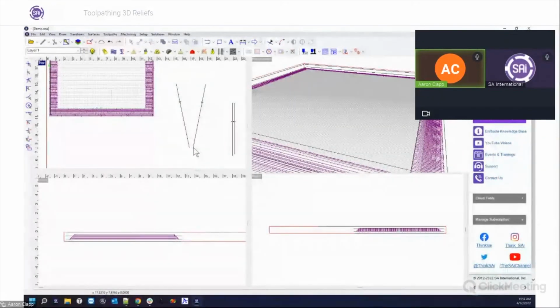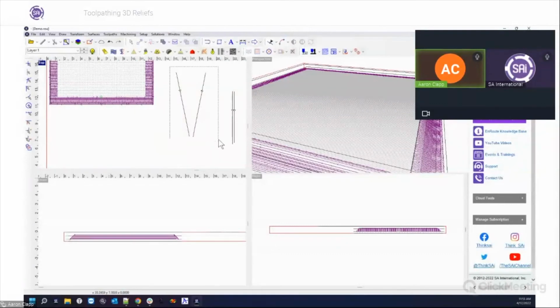Yes, there are some circumstances where the edge of the tool might hit the profile. So that's where you're probably going to have the pros and cons. Maybe you have a few of the straight end mills like this, and then maybe you have a couple of these to make up for that. But that would be one thing that I would recommend, just because those can break so easily. I know I've broken a ton of 1/16 inch end mills, and they're just super fragile. So that would be one thing.